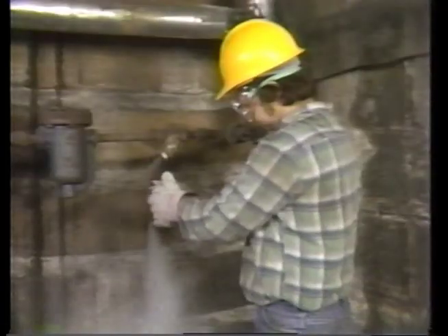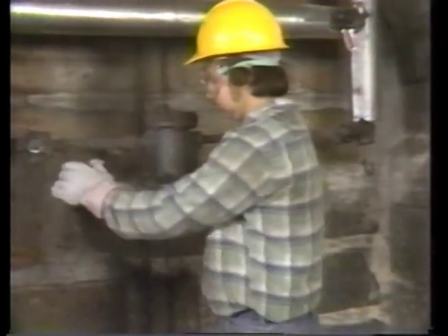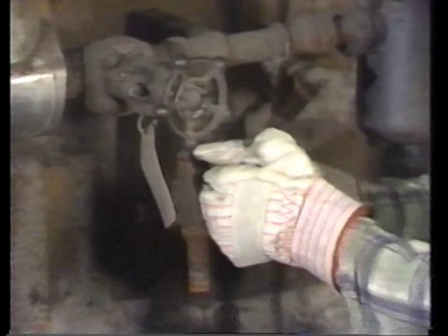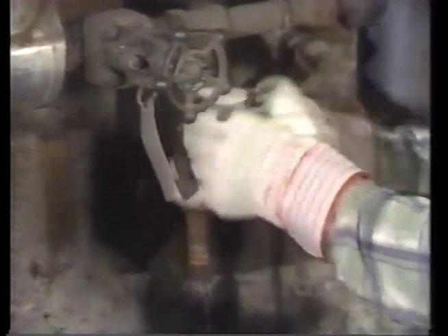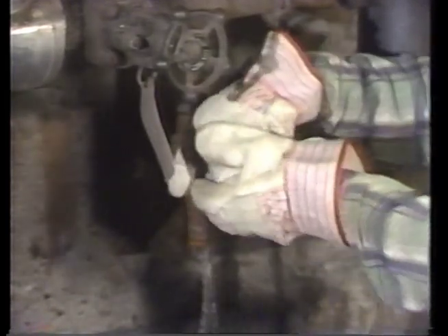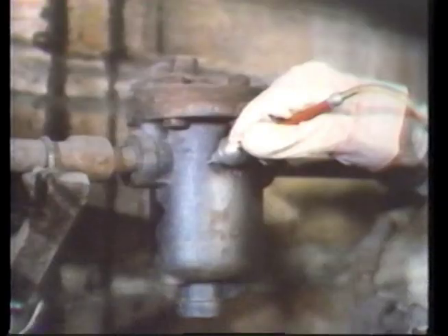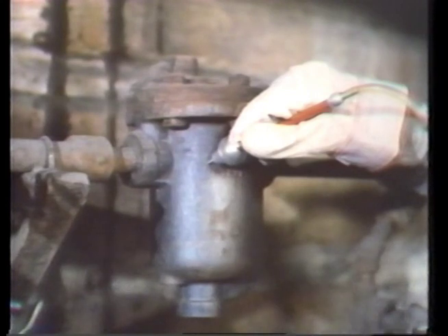Here you can see that some condensate is being discharged from upstream of the trap. If condensate is also discharged downstream of the trap, as it is here, then we know the trap has not failed shut. In mechanical traps, you will hear the flow of condensate as the bucket or float cycles. If these traps fail open, you'll hear steam whistling through the trap.